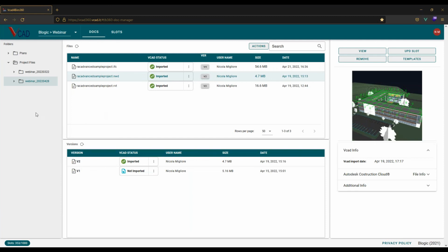Now, let's talk about the pros of the other files as well. An IFC file is good because it's an open standard. It has that intuitive structure that I showed you at the beginning. So if you want to have access to spaces and rooms, that'll be easier. It required no transformation to achieve those. And it's the file that you usually use if you are having to interact with different construction products. So IFC is usually the communication file format used. So you probably already have those.